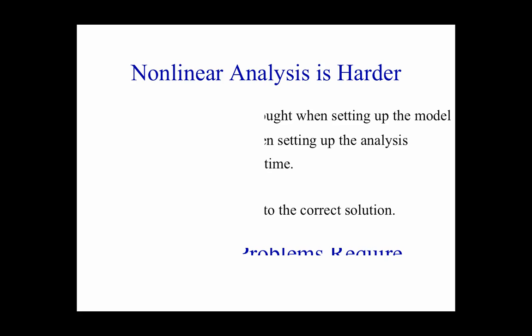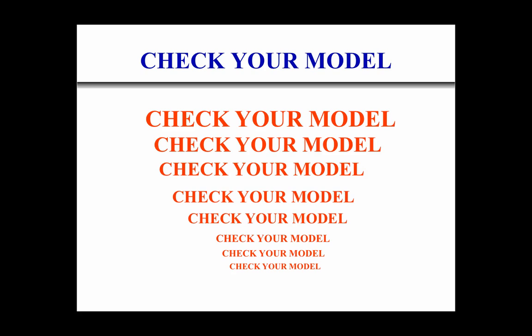So even though nonlinear is much harder, requires more time, and is not always right, typically we have to do nonlinear analysis. So we have to do it. The first thing we do is we check our model. Okay? That is the most important thing to do. That is the greatest source of problems in the analysis, is actually going to be in the model you create. So that is where you need to spend an awful lot of time, checking that model, making sure it makes sense, making sure it captures everything you think is going to happen in this structure.